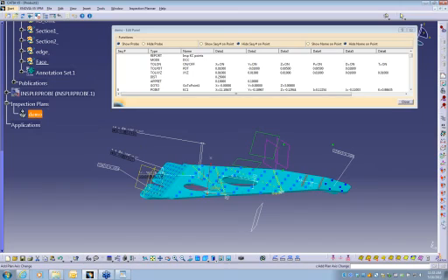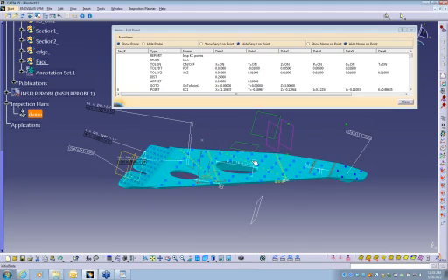During our program, we could have changed the axis. So if some of the data was called out from a different location, we could have changed the axis. We also could have, after spending all this time writing this program, had somebody come in and say, we need to go back to aircraft space. We could have picked this icon, modified plan, picked a different axis system. All this data would have been updated to that new axis system. We wouldn't have to start from scratch. So that's kind of a quick demonstration of how the planner works.